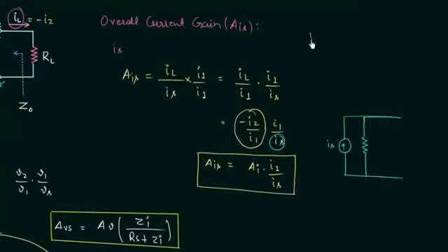The resistance RS is connected in series with the voltage source, and you want to convert it to the current source. Then you have the current source and the resistance. The resistance is now connected in parallel with the current source. This is a basic thing to do. You can also convert the current source back to the voltage source.